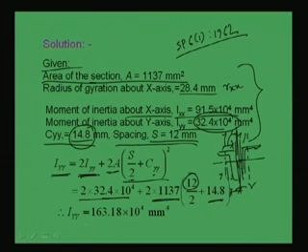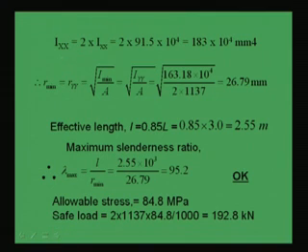So from the calculation we can find out IYY as 163.18 into 10 to the power 4 millimeter to the power 4. So this is how we can find out the IYY. Next we will find out IXX. IXX will be simply 2 into IXX, because the axis XX is not going to change about x. So 2IXX, so 2 into this is becoming this.